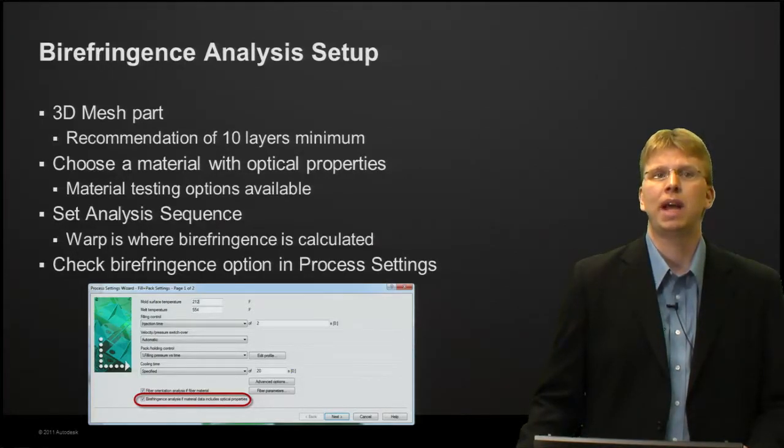Then we're going to set up the analysis sequence. The sequence has to include warp analysis. So it can be fill pack warp or cool fill pack warp. It just has to include warp because that's where birefringence is calculated.